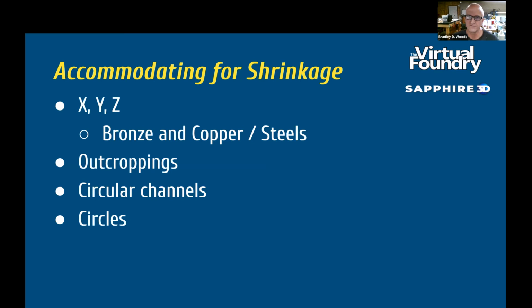So this is more a property of sintering and thermodynamics than of 3D printing or any of the materials themselves. It's definitely something to be aware of in your design, and to see if there is anything you can do to minimize that, and I guess we'll get into this with generative design, to make wall thicknesses more uniform.